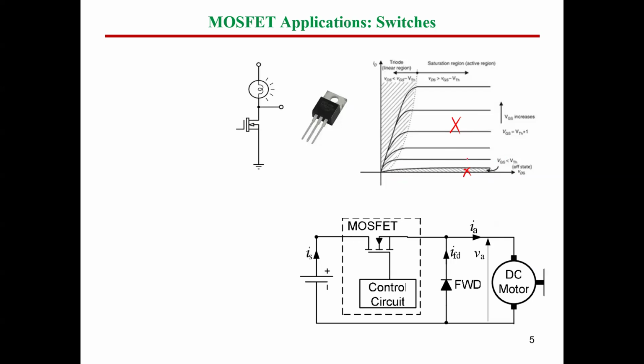So this means you don't have a high amount of current. This is number one. And at the same time, you have a voltage drop across the MOSFET. So this is V drain to source, and drain is here and source is here. If you would like to turn a switch on, you need to have this switch as a short circuit, and short circuit means 0 volt. So how come we have an operating point at this point, for instance, and it's 0 volt?